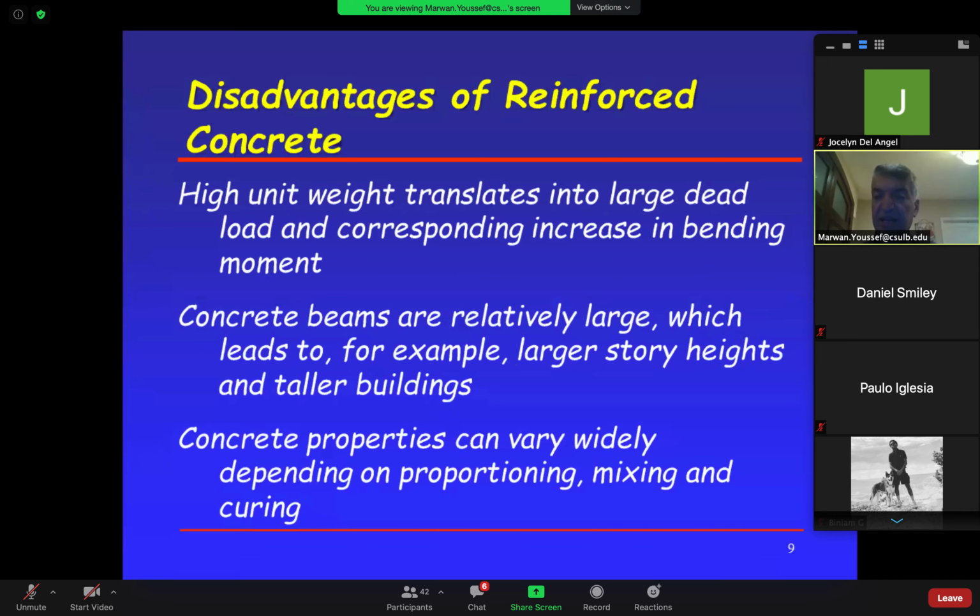You can do a mix design that gives you a concrete strength of 2,000 pounds per square inch. And we use that for what? For sidewalks. We use it for walkways. We use it for patios. But if you are doing a structural building, you need 4,000 PSI at least. You can get away maybe with 3,500, but minimum 3,000. But most buildings out there are built out of 4,000. See that? So that's why you proportion anything you want.